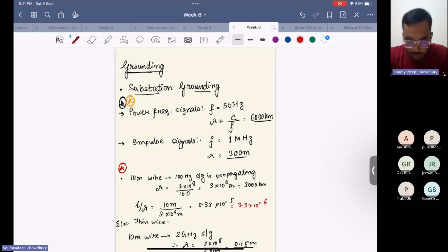So we were talking about electrically thin wires, right? A wire is thin, and we can say it from two perspectives: one is geometrically thin, the other is electrically thin. Geometrically thin basically means that if the diameter of the cross section of the wire is less than a particular value, then we call it a geometrically thin wire. Whereas electrically thin has a different perspective. We need to see whether the length of that wire is a considerable fraction of the wavelength of the